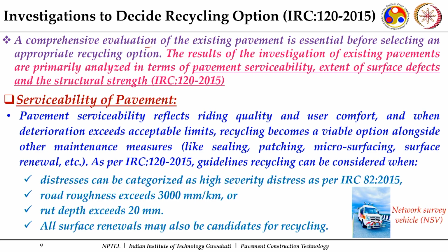recycling option. The results of the investigation of the existing pavements are primarily analyzed in three terms. One is pavement serviceability, how good it is able to serve its purpose; the extent of surface defects, up to what level they have extended; and what is the remaining structural strength of that particular pavement structure. When we talk about the serviceability of the pavement, that refers to some index which refers to the riding quality or user comfort, and when deterioration exceeds certain acceptable limits, recycling becomes a viable option.